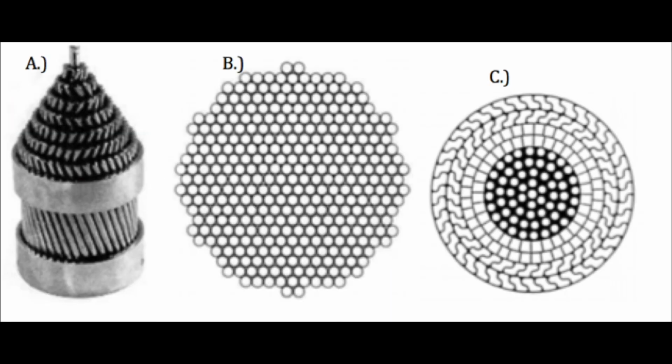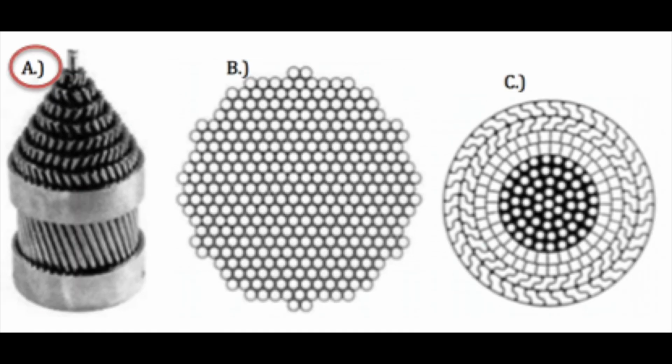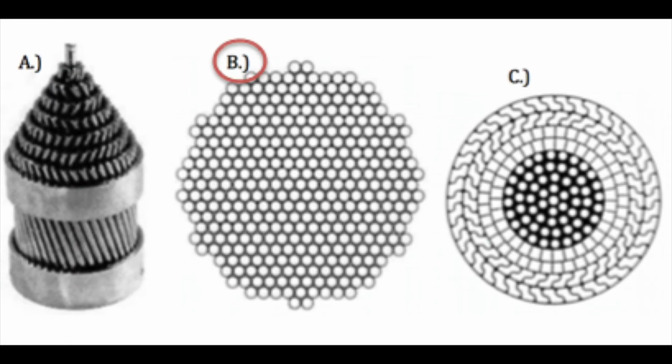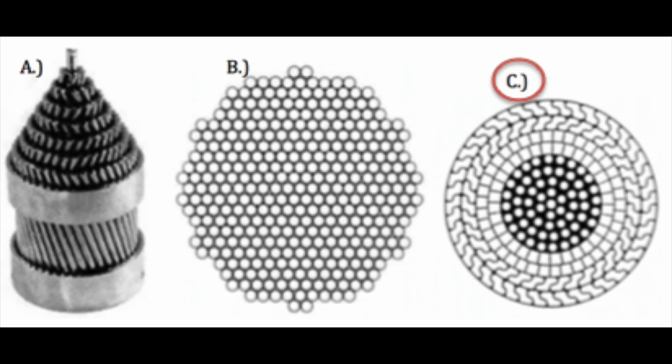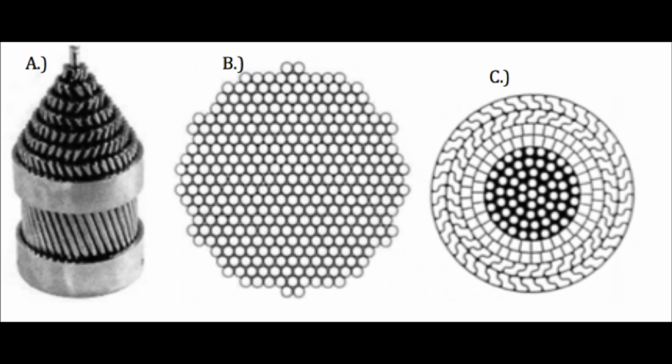Another design variable that can affect the capability of the cables is the pattern in which the cables are constructed. There are many different arrangements of the strands in cable construction, but the most common for cable stay bridges are the helically wound strands, parallel strands, and locked coil strands as displayed. Each type of cable has different characteristics, but the focus is on their tensile strength and Young's modulus of elasticity.